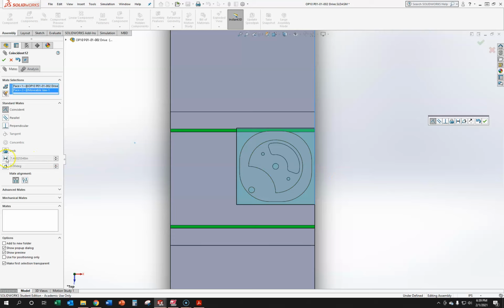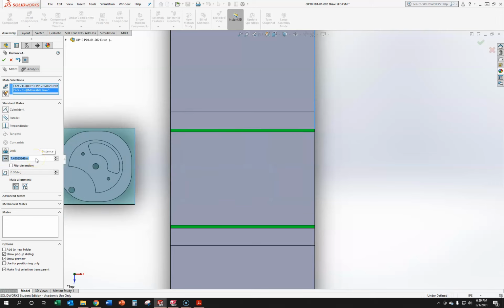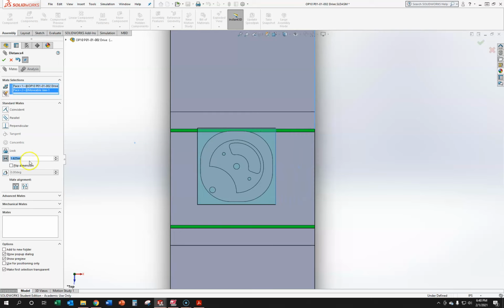So we can actually do the math in here similar to the same way we do SolidWorks. Or similar to Mastercam, so if I do 0, right, it's line on line. So then what we want to do is 3 1/4, so 3.25 divided by 2, which is 1.625, and that doesn't look right. So actually, what do we want? 1.5?